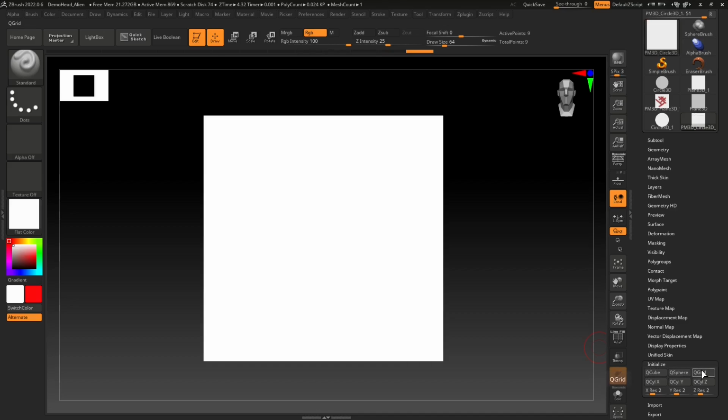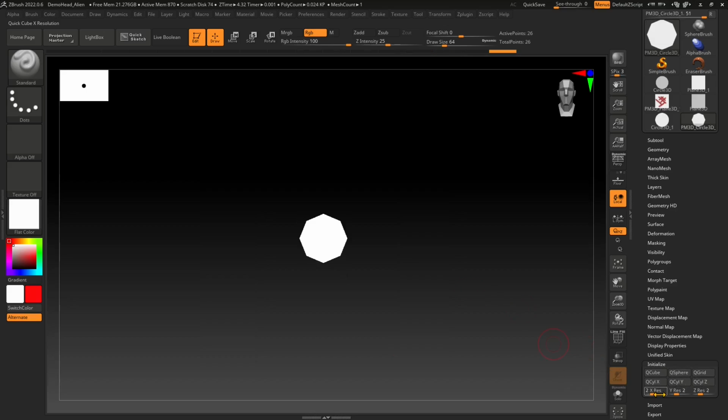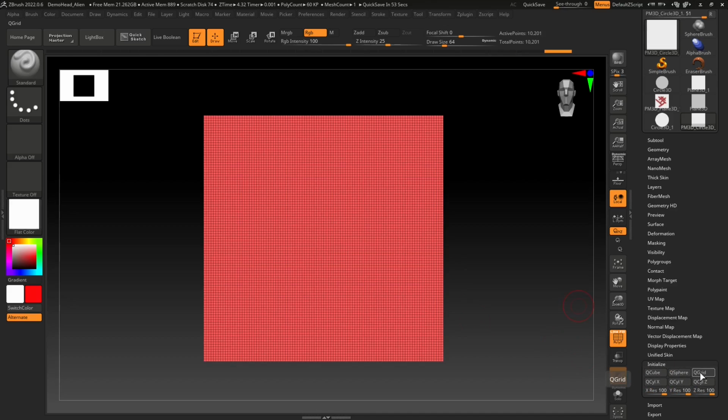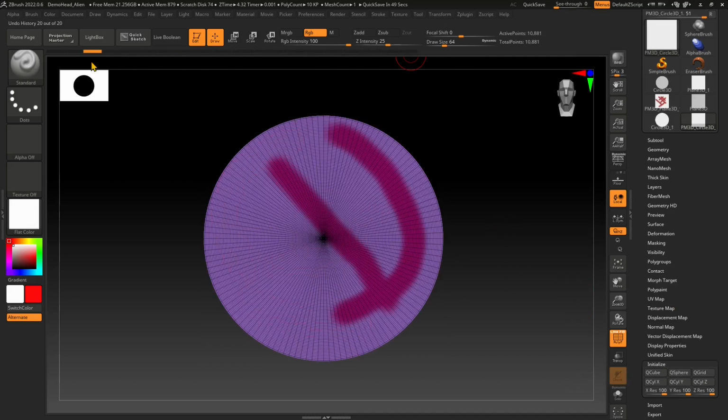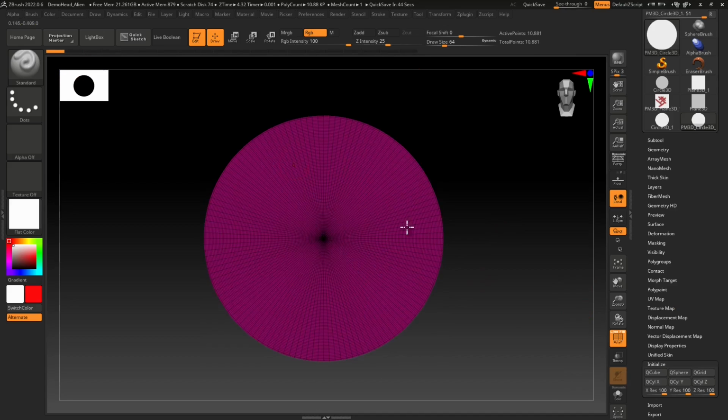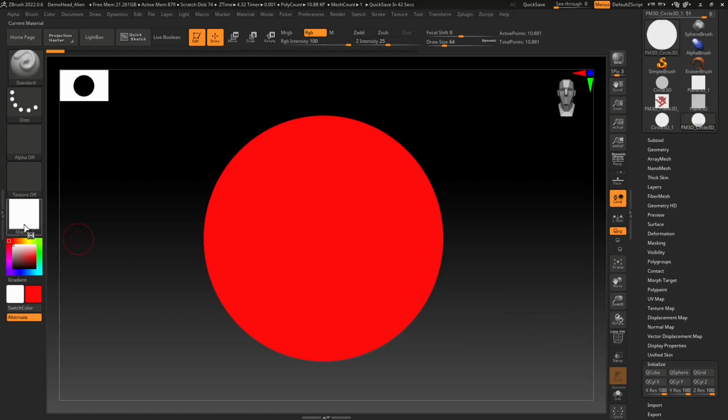Now you can see here we can just change the shape. We can use a cube or a sphere or cylinders, and also we can increase the segments, or let's call it subdivisions. So I'm just going to regenerate, just click, and you can see now they have a lot more subdivisions. So remember that the number of faces and the number of polygons are directly connected to the quality of your work and the details that you can add. We already talked about that previously, but it's better to refresh.